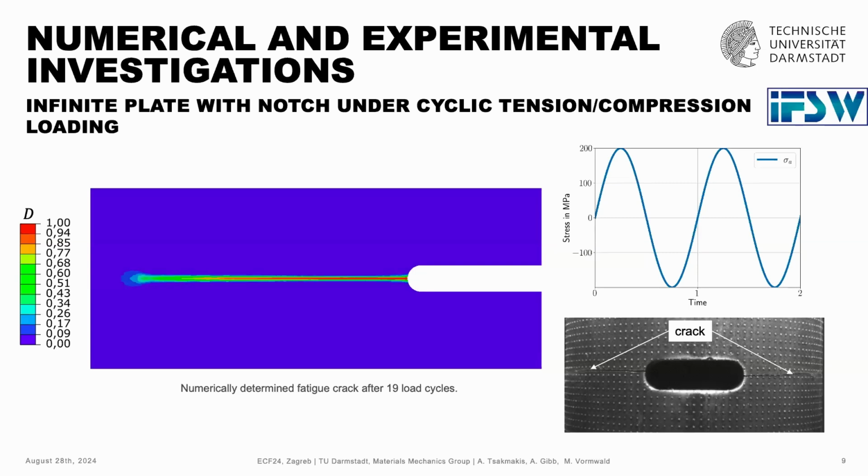We will never have larger influence of the plastic deformation than of the driving force. So the crack always grows along the horizontal axis. And that's corresponding to the experiments that our colleagues did earlier.